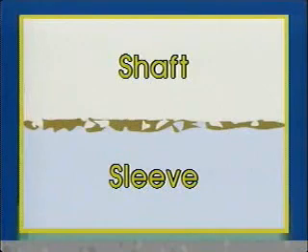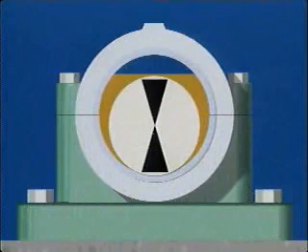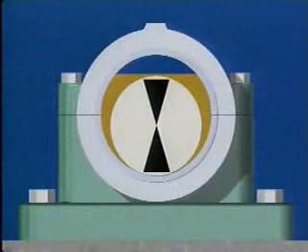Part of the load is relieved by the lubricant, but the high points of the mating surfaces take most of the load, which results in friction and wear of the surfaces. Mixed film lubrication is by no means an ideal situation, but it is a common occurrence. A third level of lubrication is film lubrication, also called full film lubrication. It occurs when moving and stationary surfaces are separated by a film of oil. Film lubrication is the preferred level of lubrication for bearings.